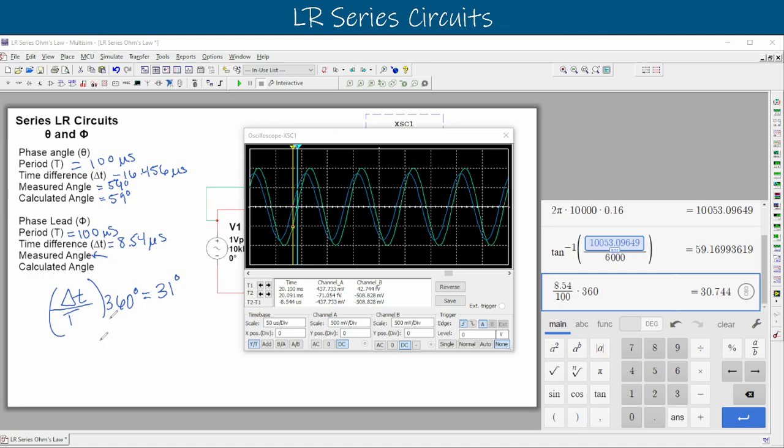So we can do the calculated phase angle. It's similar to what we did before. We did the phi before, we did our theta, right? Let's write the theta up top. The theta was equal to our inverse tangent of our linear component on bottom, our nonlinear component on top, right? And that gave us the information about that resistor. So we're going to do the opposite down here. We're going to say that our phi is equal to the inverse tan of our linear component on top, our non-linear component on bottom, right? And that focuses on that inductor. Instead, that gives us this phi symbol, right? Just like we changed our meter connections there for the same reason.